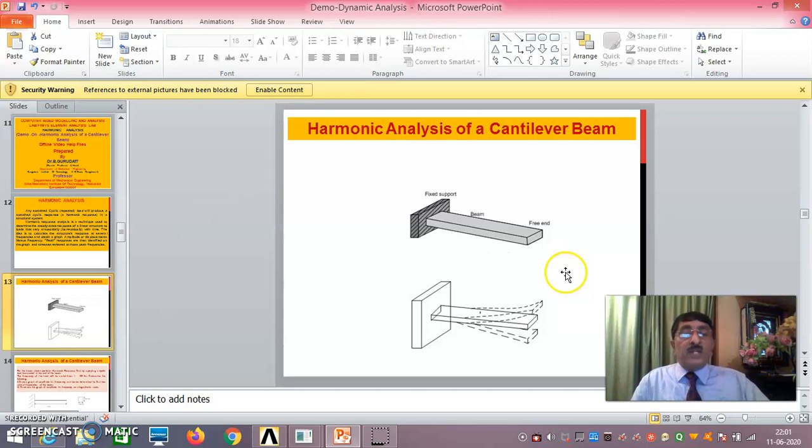Again once you come to 52, again it picks up. Then after 52 again dangerous. After 52, 60, 70, 80, 90 and all that, again it will be normal. Amplitude of vibration is normal. That means to say, by doing harmonic analysis, you will clearly know where exactly are the peaks. The peaks are corresponding to natural frequencies, what you determined already.